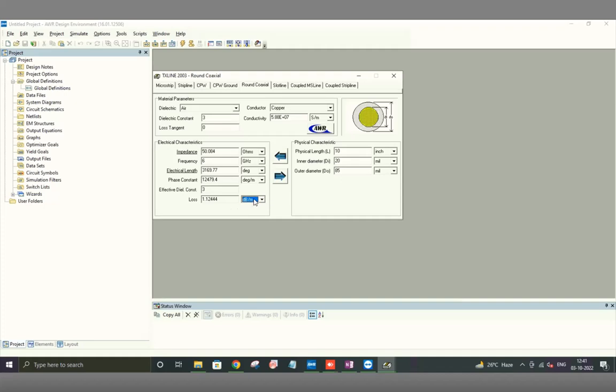To go back to what you were asking, if I wanted to change the dimension, I have to change both. If I go from 85 to say 100, but I want to retain 50 ohms, now this is going to make it 55. So I'll have to increase this so that it comes back. Okay, that was too much.